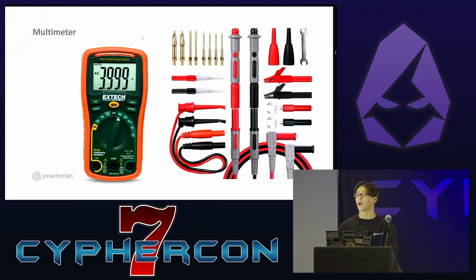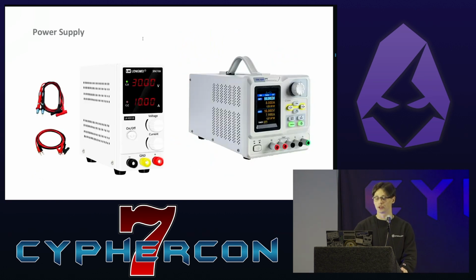So if you're trying to figure out where one pin is connected to, you can hold one lead on that pin and probe around to all of the test pads or other pins or components, and when you hear a beep, you know that's where a connection is. I also recommend getting a set of leads, having some finer point tips, some alligator tips, and some retractable spring-loaded clips can be really helpful for different circumstances.